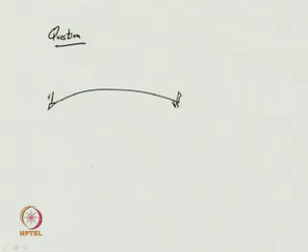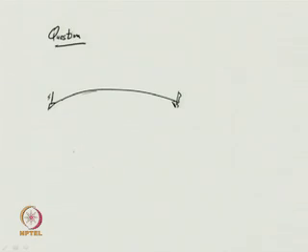You can also use your overland flow approximations along these portions to find the discharge or discharge per unit width, and then arrive at the discharge quantity here, then subsequently incorporate uniform flow along this main triangular gutter channel. If I just show it in an elaborated way, it may look like this, something like this. So, this is your triangular main channel, water may be there.